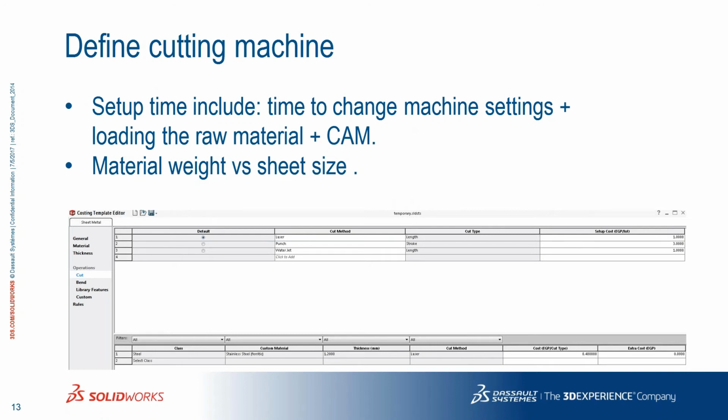So while the machine is in the workshop, if you look at the time after unloading the material, actually this is also a setup time. So once the operator clicks stop or pushes the stop button to unload the material, till he gets the cycle going again to machine another part, all of this time you should consider a setup time. And to understand the cost of this time, you have to understand how many laborers are standing and helping serve the machine. And you have to multiply this time by the labor cost. Then in that case, you will be able to get the setup cost. That's simply the setup cost. First, you have to convert it to time, and then you will be able to have the cost.